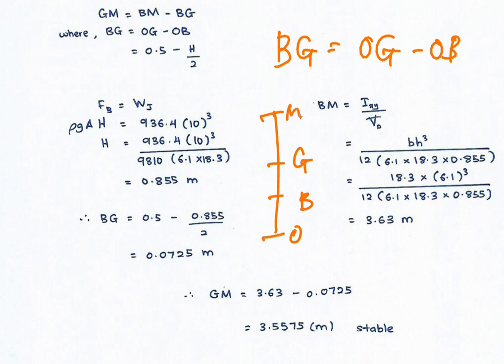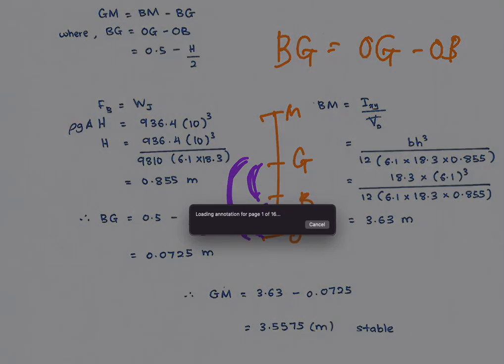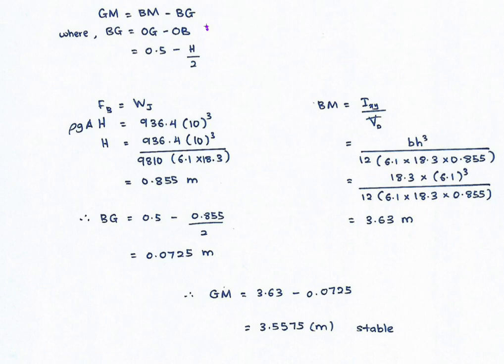OBGM. So to calculate BG here, it is equal to OG minus OB. The unit is in meters, so it is a vertical distance from that specific point. Then from this calculation, our aim is to fulfill this equation. So we need to know the value of GM.